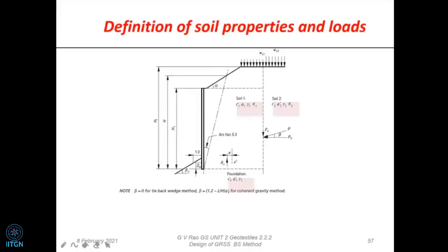And the next stage, of course, is to go into the actual definition of soil properties. Now, what is the definition? In the definition, what is it we got? I mentioned it last time, but it is worth noting that we got a foundation soil. We also got a soil which is going to give you the earth pressure, for which we have designed the entire thing. And then we got a chosen fill soil, which you are going to pick up.